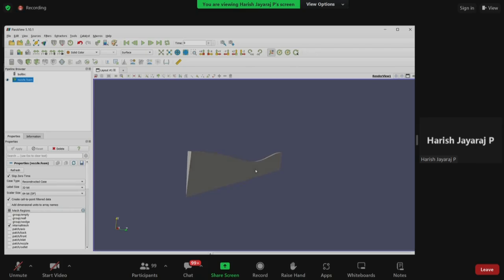Why are we doing this instead of running the entire geometry? To reduce the number of cells. When you run the simulation, you will know it is taking a lot of time to end the simulation. As the number of cells increase, as the geometry gets bigger, the time taken will be longer as well. So to reduce or simplify the geometry as much as possible, we are taking only a small wedge of the nozzle and we are viewing the results.